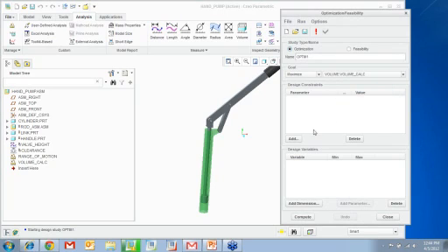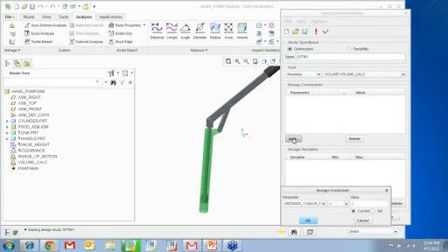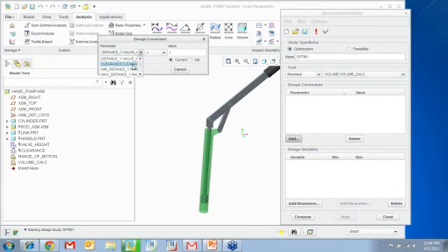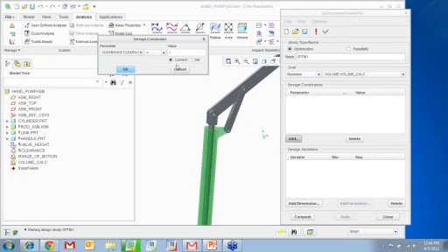Okay. Now, the constraint that I'm going to add is that I don't want any interference. See that little clearance between this part and this part? I'm going to say that clearance should be more than or equal to 0.25. Okay, that's what I want to stay at.